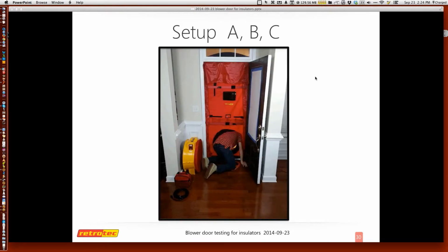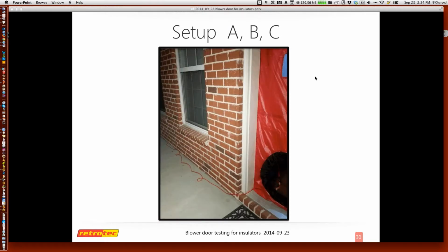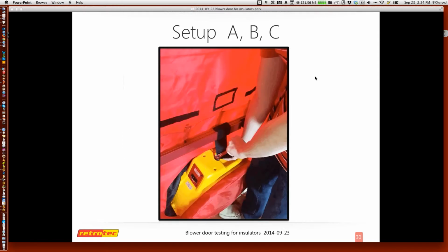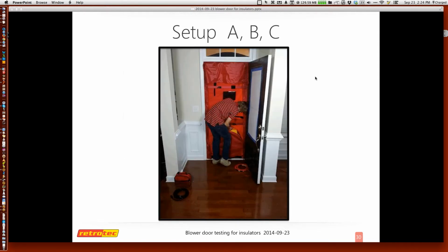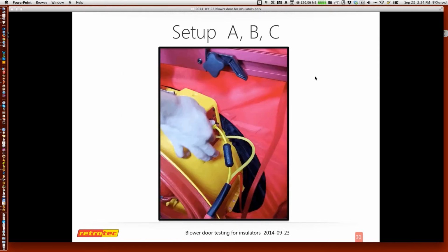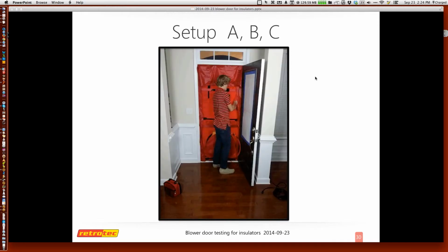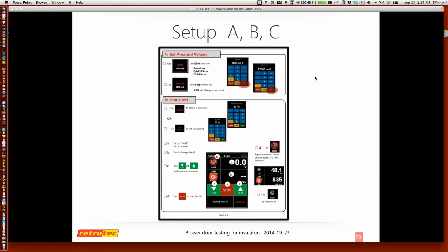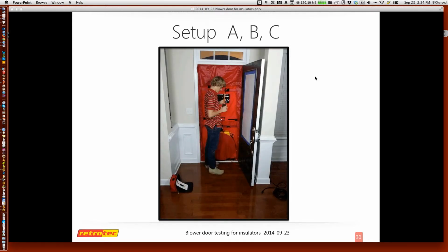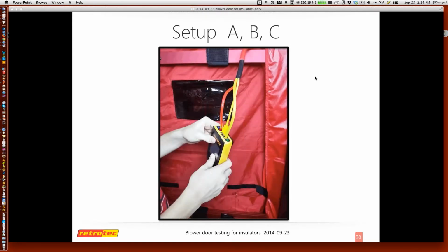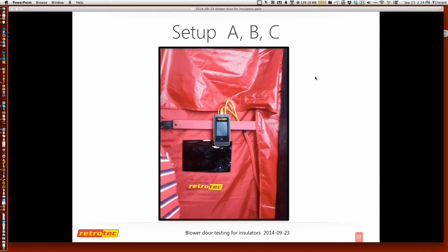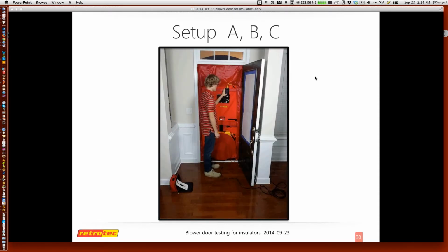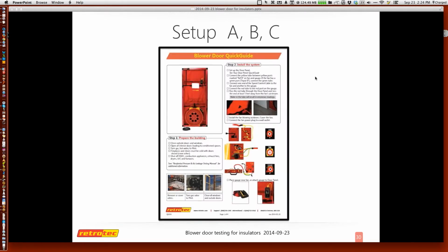Most of the other setup that goes along here is all easily followed by the quick guides. You do want to make sure that your reference tube is as far away from the fan as possible outside. It should not be in water, or if it's a really windy day, you may actually extend that tubing so it goes around other parts of the house. Jay actually has a variety of methods of putting it in a system where it actually has dirt or you can bury it. But your goal is to make sure that it actually is not really sitting directly in the wind.